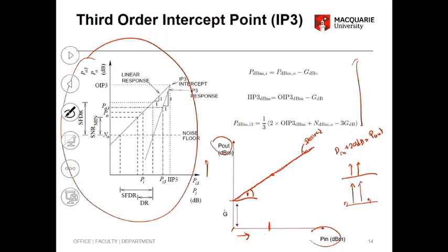And that power level initially is lower, because this level is lower than that, starting here, and then as you increase your input power, this tends to go up, right? But they tend to go up faster than your desired signal output. Okay, so that's a measured plus the theoretically derived formula, but you don't need to know how to derive it. It's just that you need to know it. They tend to go up in the gradient of 3.